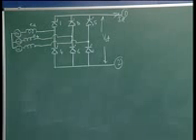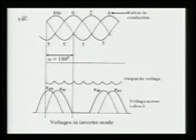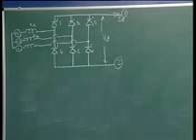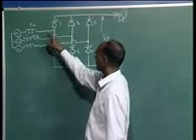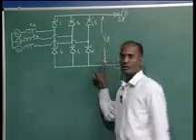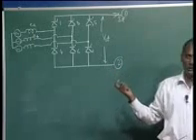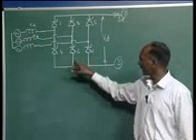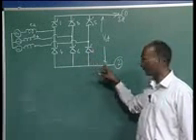Now you can also see, if valve 4 is conducting, what the output voltage at that limb will be. Valve 4 is connected to phase A, so if it is conducting, the voltage appearing here is the phase A voltage, EA. Similarly, if 6 is conducting, then EB; if 2 is conducting, then EC.